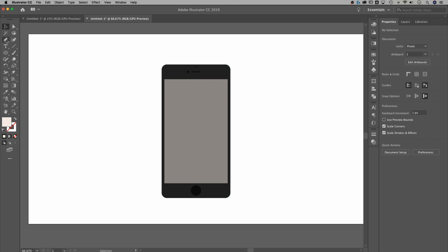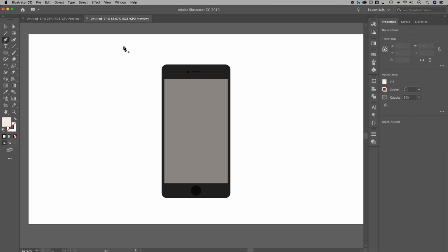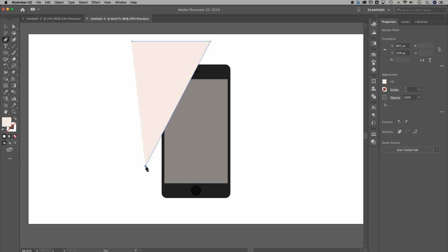All right, so I think the easiest way maybe here is to go grab the Pen tool. Shortcut key is P. I'm gonna create a point out here. I'm gonna create a point somewhere randomly over here, and then we're gonna create a point down here. And this is gonna dictate where it crosses over. So I want it to maybe be like just this upper left-hand corner right in there. And then the last thing I'm gonna do is close up this path. So not anything too complex with the Pen tool. Didn't even hold Shift. I just clicked 3 points and made a triangle.